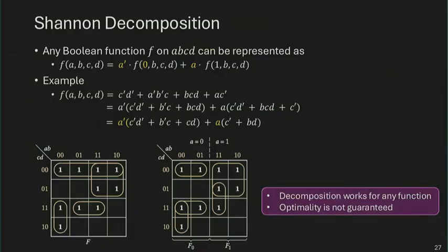All right. So this idea of mux implementation really boils down to the concept of Shannon decomposition. Shannon decomposition is a theorem saying that any function, you can decompose it into two phases. By assigning a variable to 0, you do one implementation. By assigning the variable to 1, you do a different implementation. Each of these implementations is a smaller implementation compared to the original function.